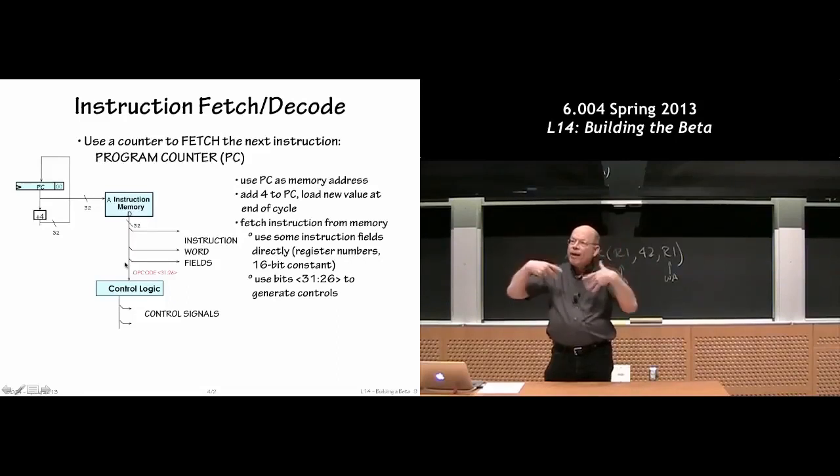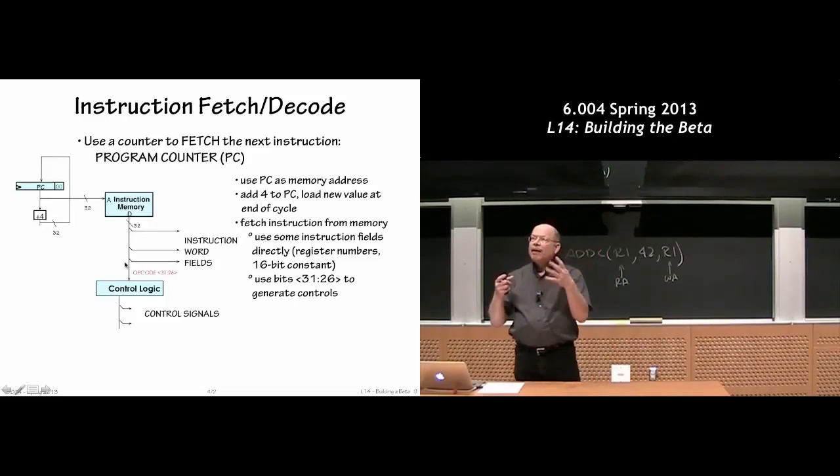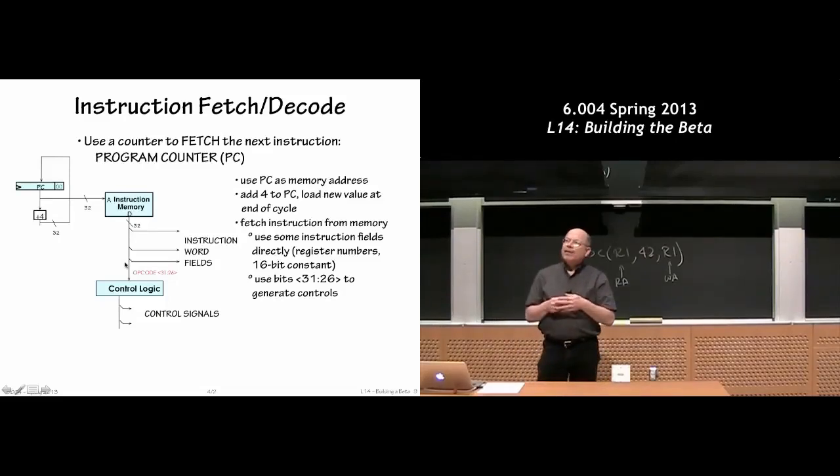So we'll always be fetching 4 bytes at a time. And by convention, we always choose to fetch bytes at a 0 mod 4 address. So we'll fetch a word from location 0 and from location 4 and from location 8 and from location C. I'm just counting up in hex, counting by 4.